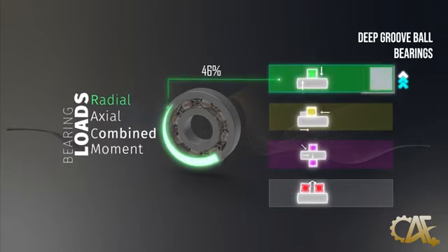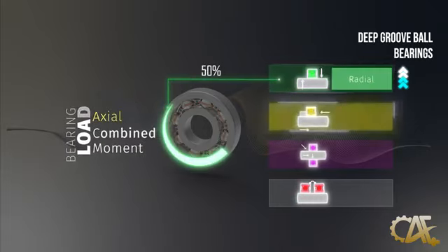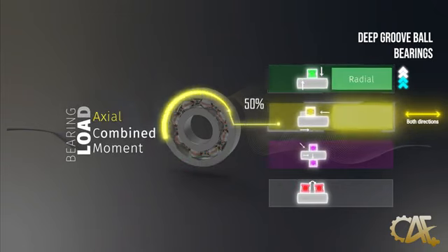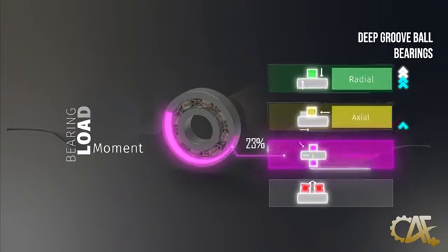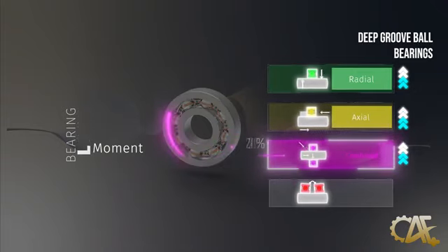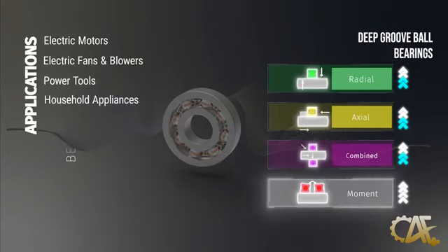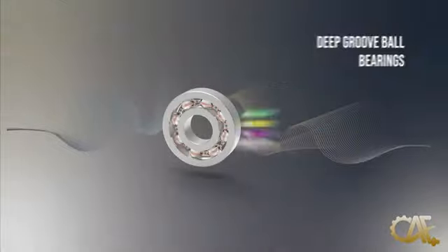Deep groove ball bearings excel at handling moderate radial, axial, and combined loads. However, they aren't well suited for moment loads. Due to their proficiency in managing moderate loads, deep groove ball bearings are ideal for applications such as electric motors, fans and blowers, power tools, and household appliances.